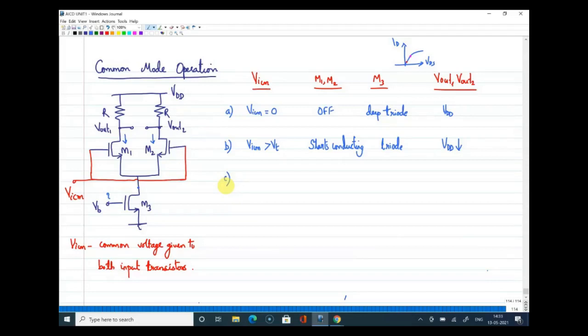All right, so for the transistor to be in saturation, so for M3 to be in saturation, the drain voltage should be minimum. This VDS should be some minimum voltage, and we generally call that the overdrive voltage or VDS sat of the device, so VOV3. And along with that VOV3, I should also have appropriate VGS here so that a current will flow.